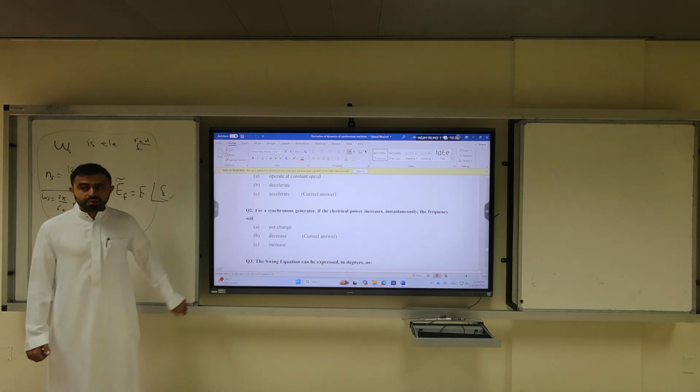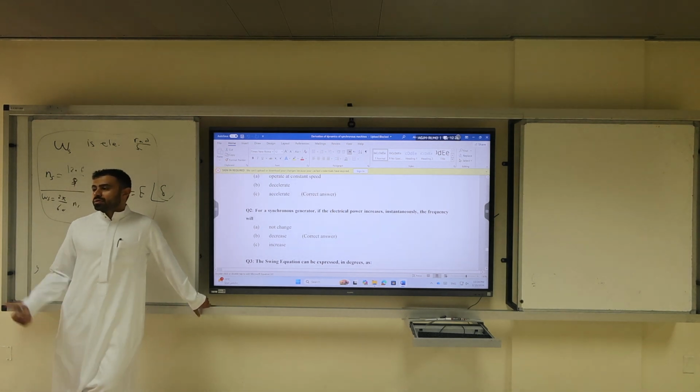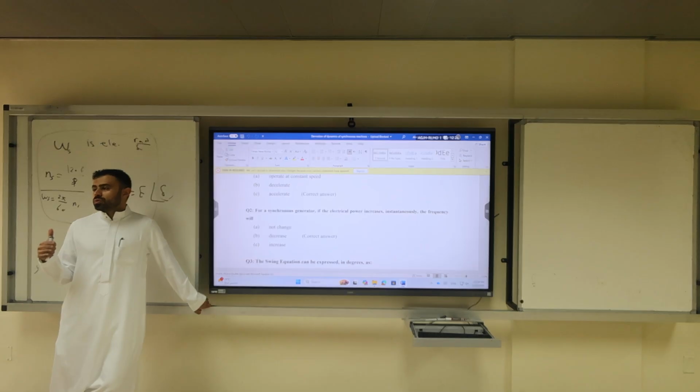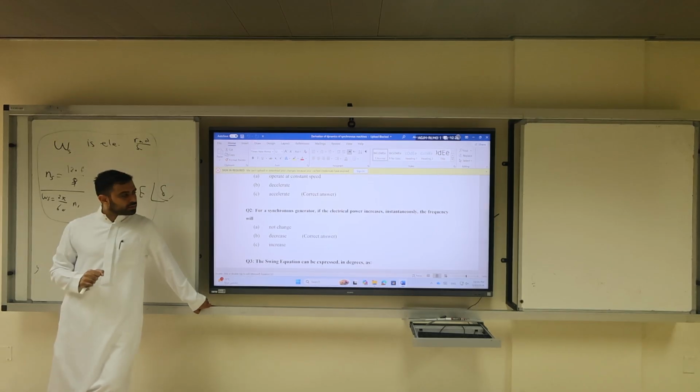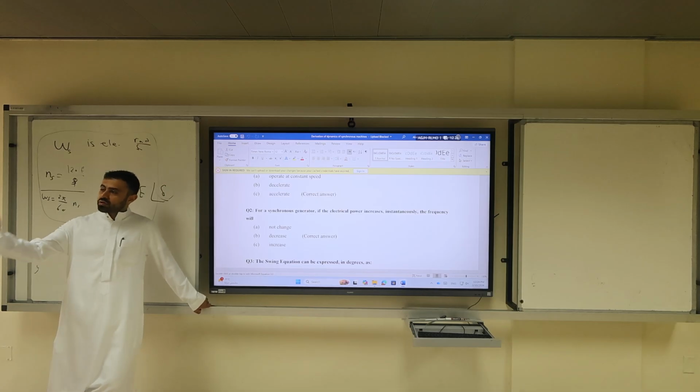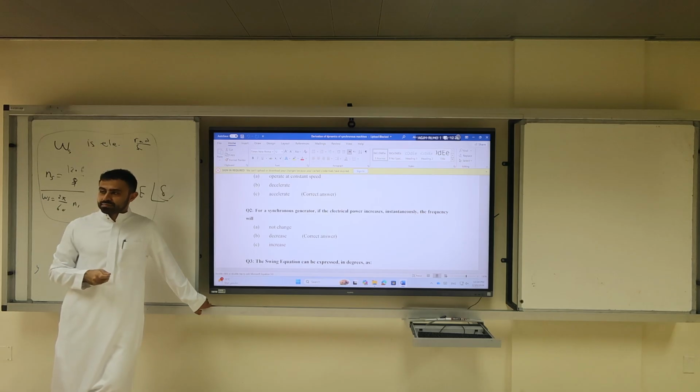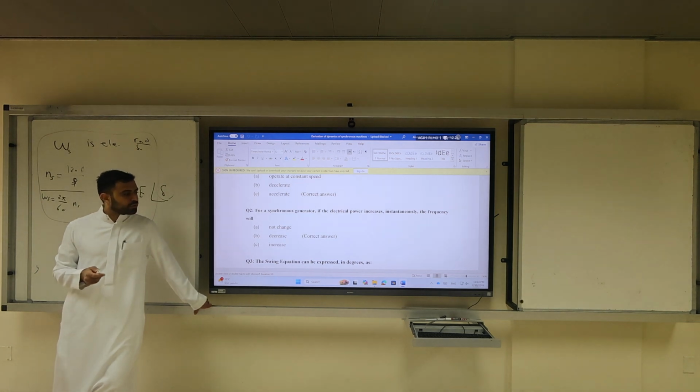It has to do with, if you increase the power, you reduce the power factor. If you increase real power, you increase the current. What will happen to I_a? Decrease. No, increase. What do you think? For a synchronous generator, if the electrical power increases, what will happen to the frequency?